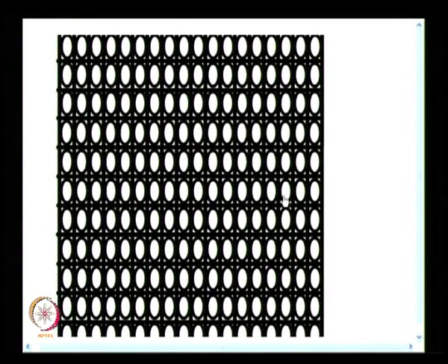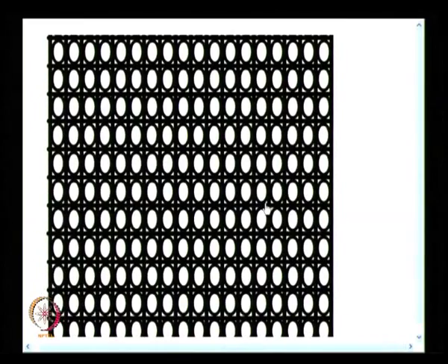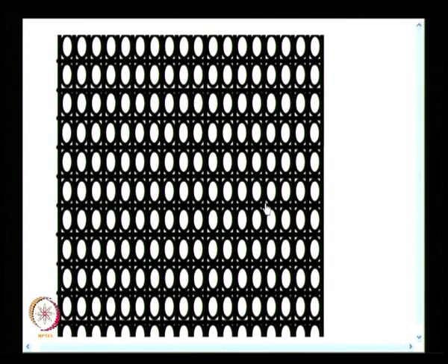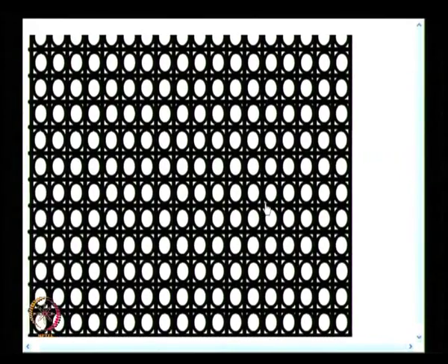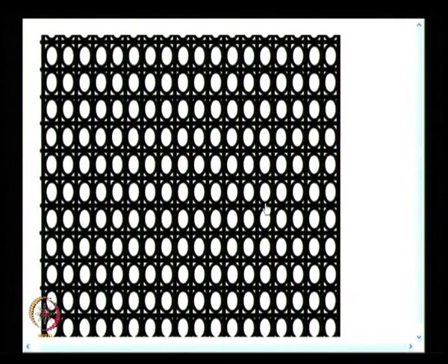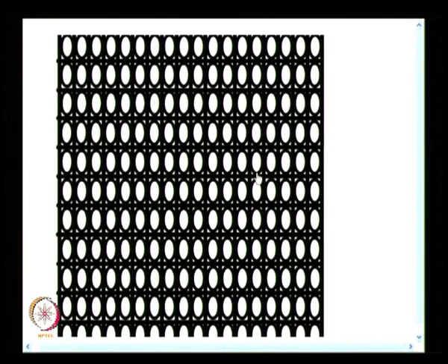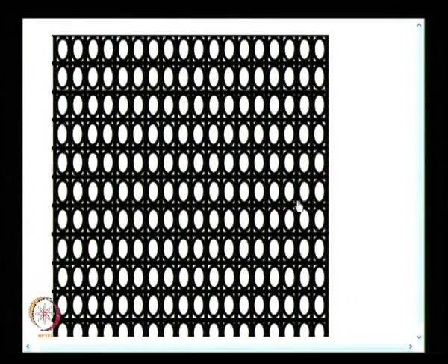Can you see that? So, you also find the stretch direction, and by looking at the change in the geometry of the circle, you will also be able to find out some information about the major strain axis, minor strain axis, and so on and so forth. So, if you also put a circle in the grid, it has its advantages. I have a circle that gets deformed to an ellipse.